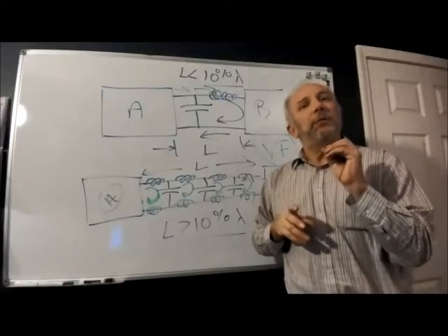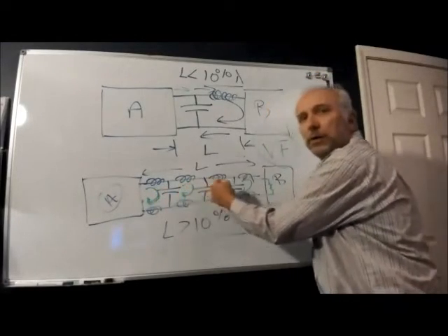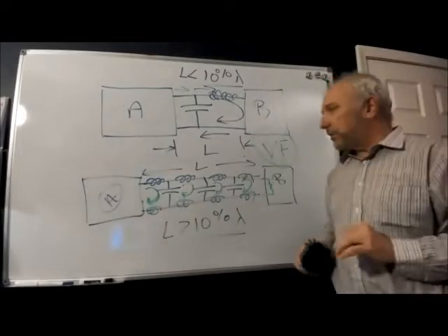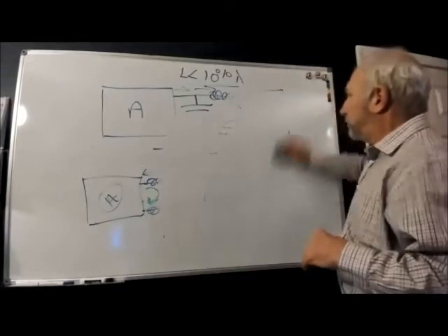All right. But the important thing is what? The important thing is we recognize how that energy propagates along the transmission line. A key parameter in the case of a transmission line is known as the characteristic impedance.